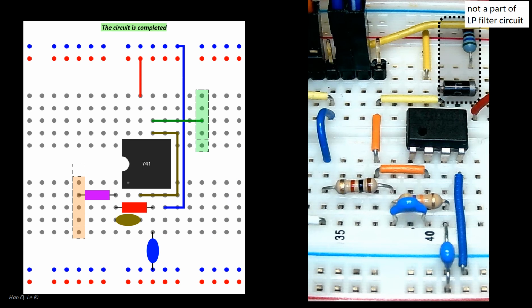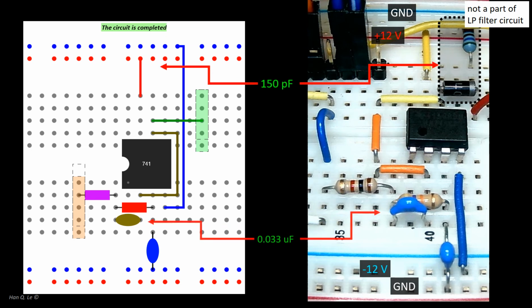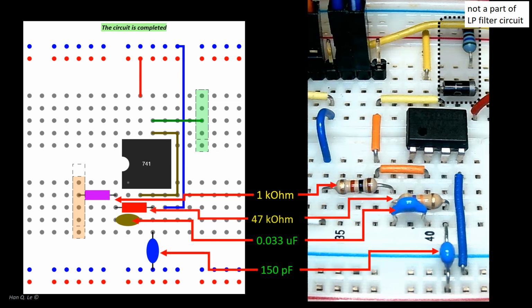This photograph shows a representation of this high-pass filter circuit. A difference from the schematic is the power rails. The plus and minus 12-volt supplies are on two separate inner rails. The ground is on the two outer rails. The photograph is intended to have sufficient spatial resolution and color clarity to allow the reading of the component values as shown, which can be used to build the circuit.